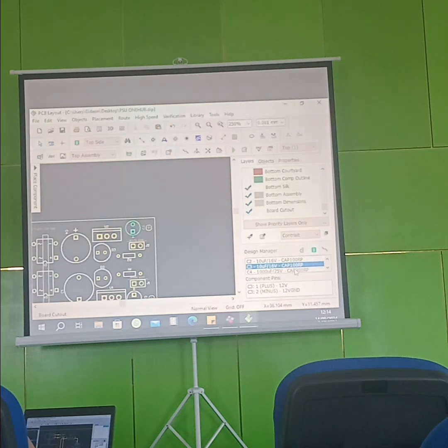This pick and place file gives the X, Y, Z, orientation, and value of all your components. You can limit what you want the software to do. If you negotiate with them to buy your components for you, you are going to give them X, Y, Z. X, Y is the coordinate of where each component will be, and Z is the depth.